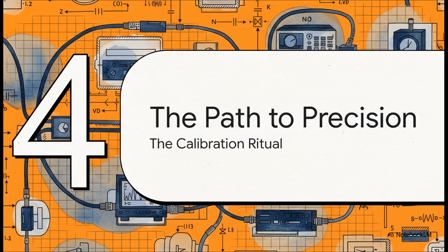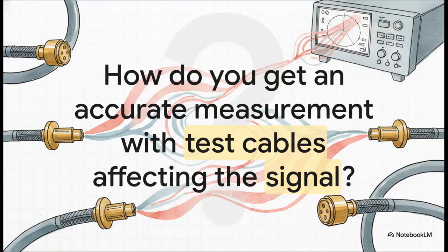So this is great. We've got our map, the Smith chart, but before we can actually trust that map to guide us, we have to make sure it's dead on accurate. And because a VNA is such a ridiculously sensitive instrument, we have to be super careful and account for everything in our test setup. And that leads to a really critical question, right? Think about it. The signal from the VNA has to travel through your test cables and connectors just to get to the thing you want to measure. And those cables, they add their own delays and losses. If we're not careful, we'll end up measuring the cable itself instead of the actual device we care about.